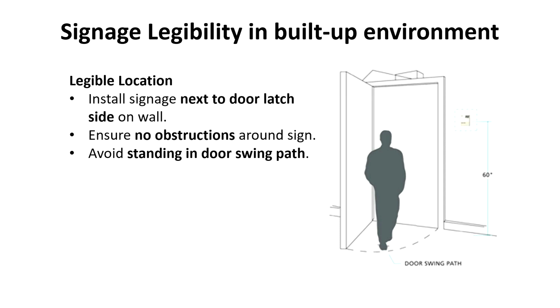It is advised that there be no obstructions around the signages. This means the area surrounding the signage should be clear of any objects or obstacles that could create a blocking or hindrance in visibility. The instructions also recommend avoiding placing signage in the path of the doorway. Placing the sign in this location could potentially obstruct the door movement, posing a safety hazard and inconvenience to individuals.